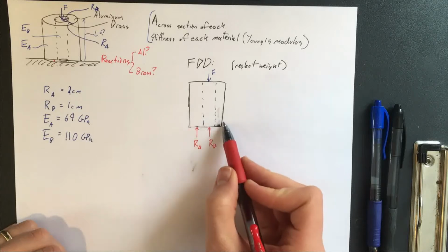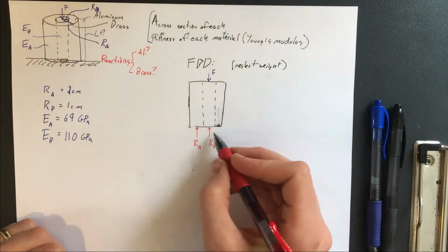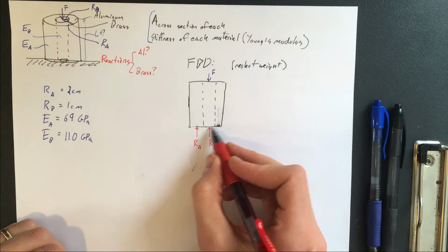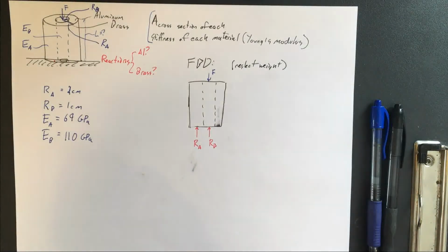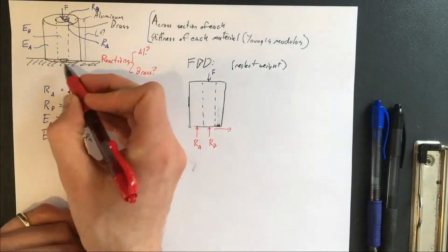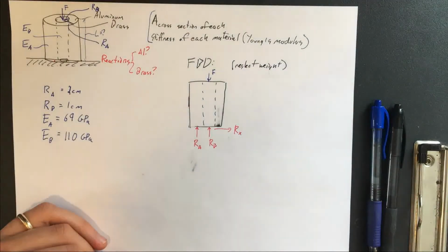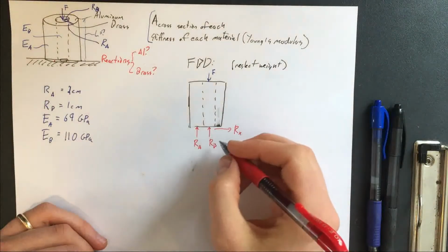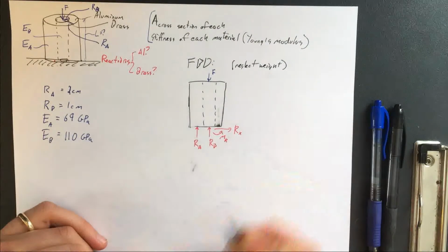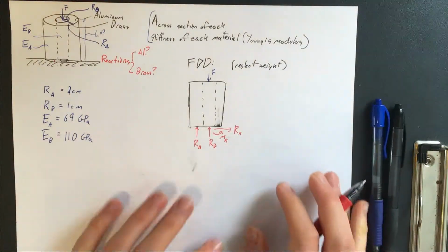Strictly speaking, this reaction force to the aluminum, I'm drawing it here, but we would know it would apply to the whole annulus shape of the aluminum. It's actually applied to both sides because it's the whole ring around. Strictly speaking, to be complete, because this is a connection that's rigidly attached to the wall, there could be some X reaction force, and there could be a reaction moment as well. We'll square these away in just a moment.